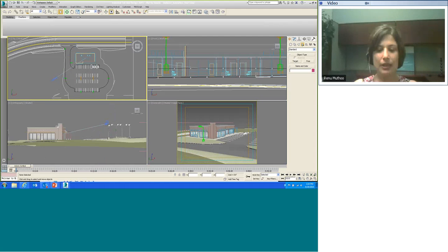So down here, as I was talking, this is the time slider, as you can see, and it shows 0 of 450, which shows that the SMPTE mode has been selected for the display of the time slider. And this is the track bar, which shows all those where we can set the keyframe. So first of all, we need to set a few animation controls that are available in the groups right here. So beginning from the set keys to all, these are the playback controls and things like that.